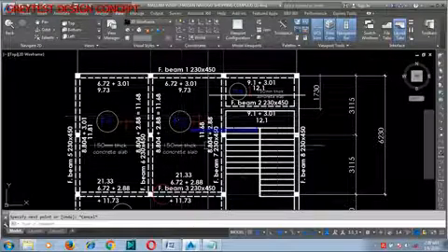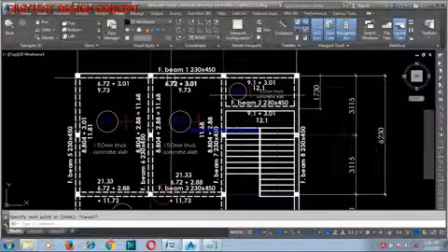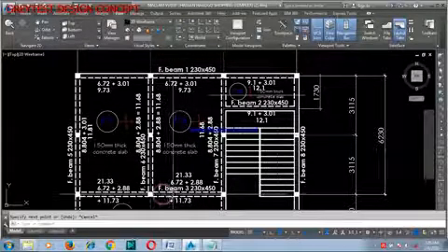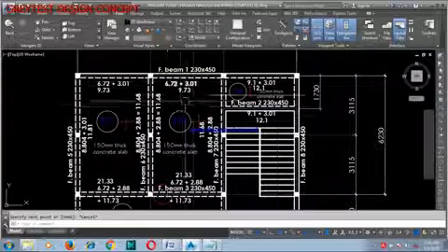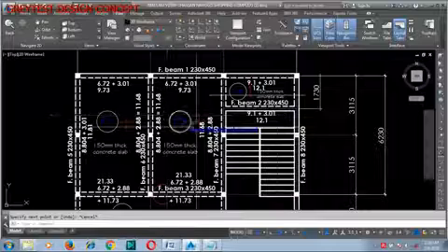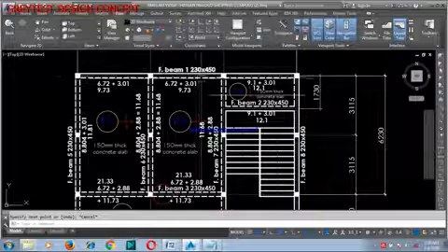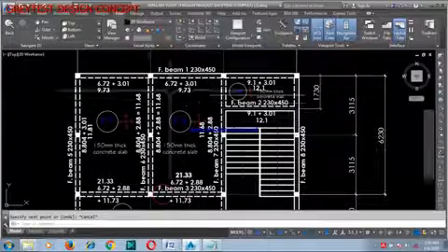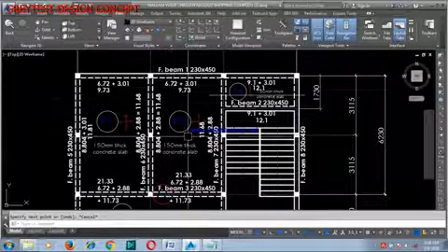Now on that short span, we have two short spans on this particular panel. We have this one, then we have this one, right? That's beam 1 and beam 3. That's this particular span on beam 3. So when you divide 13.431, it gives you 6.72. You share it into 2. Half is taken by this beam, half is taken by this beam, in these particular spans. Okay, if that is correct.